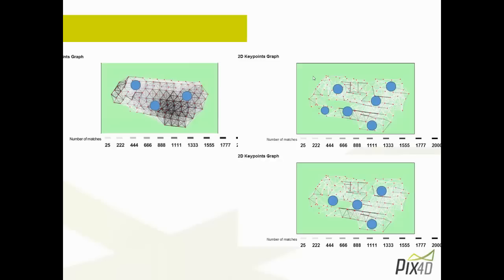You can see that the visual content is so low in the images that there is potentially much more error accumulation happening in this project. Another thing you can see is that this project almost divided itself into two parts, the part on the top and the part on the bottom, and there's very little link between these two parts. In this case, adding more than 3 ground control points can really help and improve the accuracy, and is probably needed to improve the accuracy.